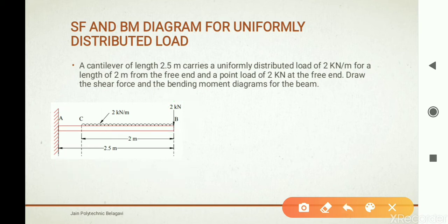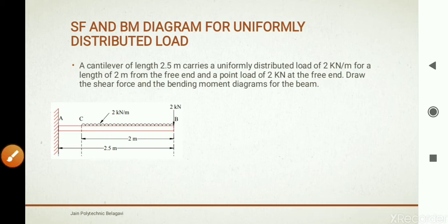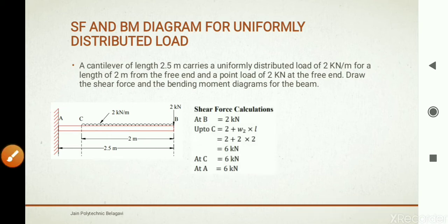Now, shear force calculation first and foremost. Shear force at B is nothing but 2 kN, because beyond B there is no load, and exactly at point B, a point load of 2 kN is acting and itself will be the shear force. Shear force till point C.